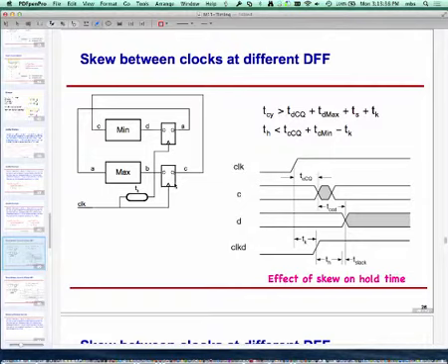So for example, in this case, the clock edge arrives at the top flip-flop a little bit later. There is a little additional delay it sees, T sub k. This is called the clock skew. So if I'm looking at a particular clock edge, it might arrive at, let's say, time t out here, but it will arrive at time t plus T sub k out here. And that messes things up additionally. I have to factor those in also.